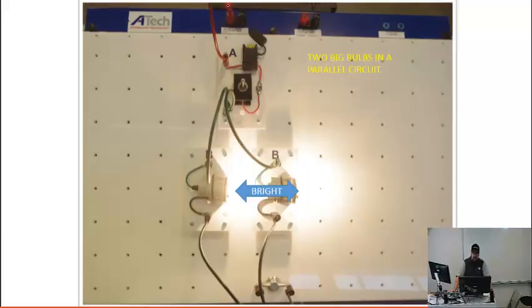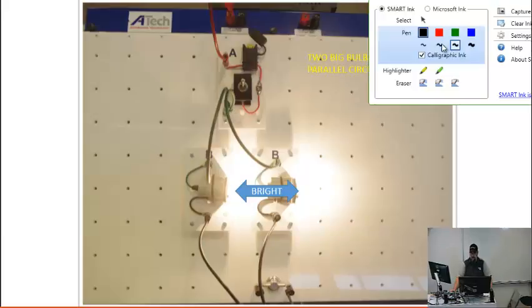So we come out of our power source with our red wire. We go through the fuse, through the switch. And then from the switch, I have two wires going out. So I'm splitting the wires off. Now, what happens is if I have 12 volts at the top here, I'm going to have 12 volts here and here. Okay, so let me go ahead and select my pin again.